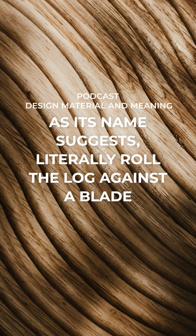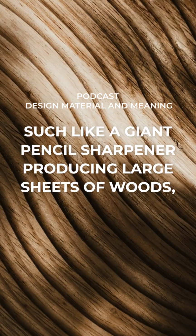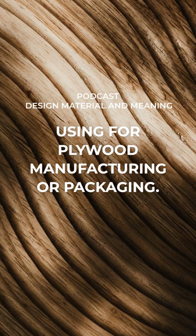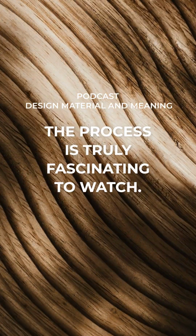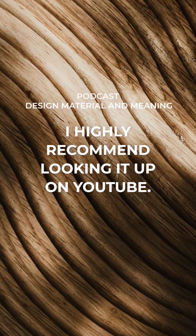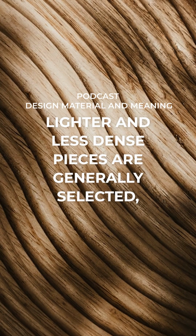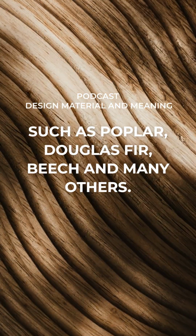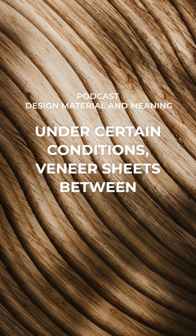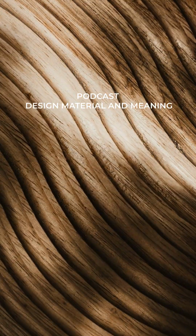Peeling, as its name suggests, literally rolls the log against a blade, like a giant pencil sharpener, producing large sheets of wood used for plywood manufacturing or packaging. The process is truly fascinating to watch. I highly recommend looking it up on YouTube. To facilitate this process, lighter and less dense woods are generally selected, such as poplar, Douglas fir, beech, and many others. Under certain conditions, veneer sheets between 0.5 and 10 mm thick can be obtained.